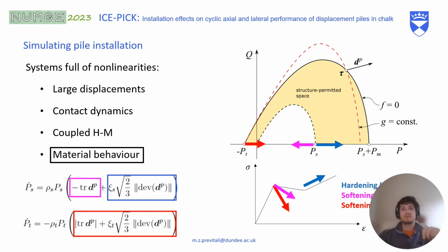You can see on the bottom left that PT, the strength of the bond of the material, can only decrease with plastic deformation, for both volumetric, here on the left, and deviatoric, while the size of the yield surface, PS, itself can change depending on the volumetric deformation.